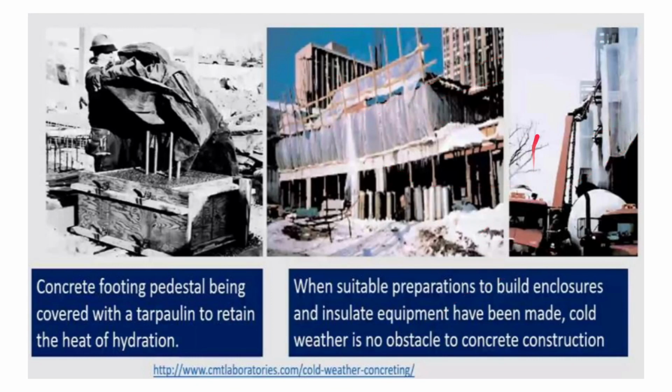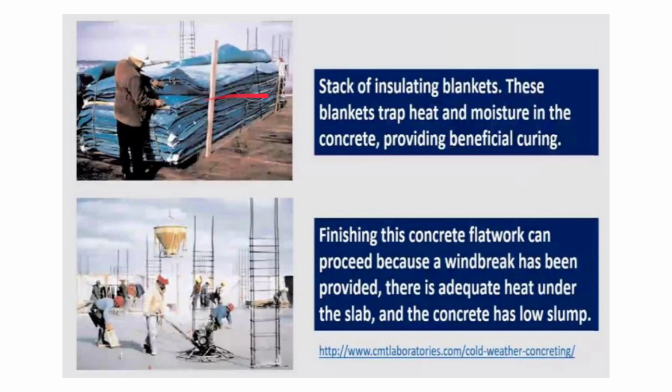So that is the factor. Cold weather will not hamper us if we adopt proper practices. Here we can see a stack of insulating blankets, okay. These blankets trap heat and moisture in the concrete, providing beneficial curing in the form of membrane curing, okay. So mostly membrane curing is used in the case of cold weather.